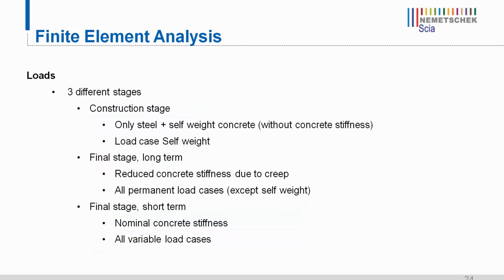Next, the different load cases in this CAM model or composite analysis model. Construction stages have to be taken into account in analysis of composite structures, mostly for two reasons. First, the profile steel sheeting is used as a formwork for the concrete topping, so it has to carry only the weight of the concrete. And the second one is that the behavior of steel and concrete are fundamentally different. Keep in mind, for instance, the stiffness is different, effect of creep, and so on.